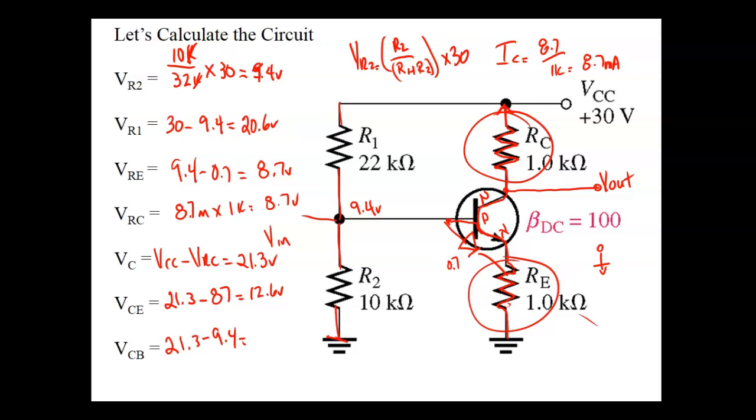Now, if I could bring an AC signal in somehow, this is not a good amplifier. This guy right here would only have a gain of 1, by the way. We'll figure out how we calculate that. A voltage gain of 1 means it's a waste of time, but it's good to learn how to calculate these things, right? Now, why couldn't I bring an AC signal directly into the base? We demonstrated that in class the other day.